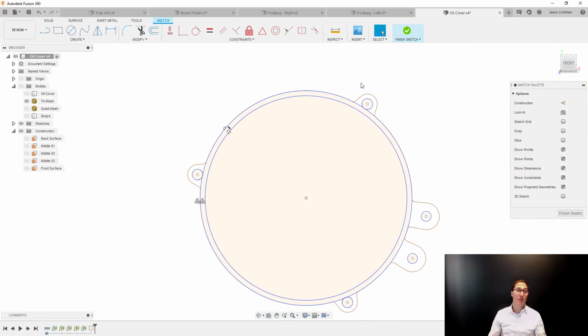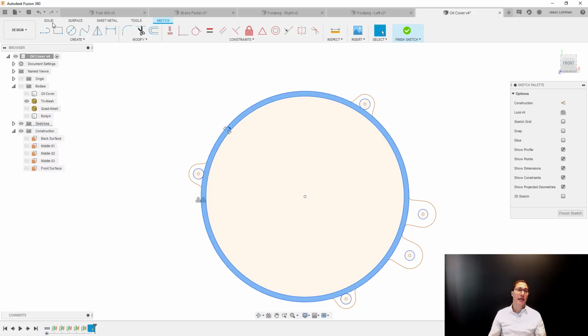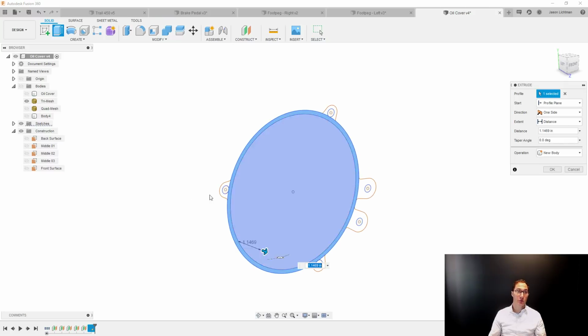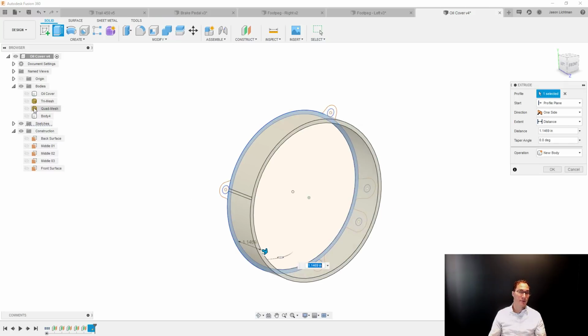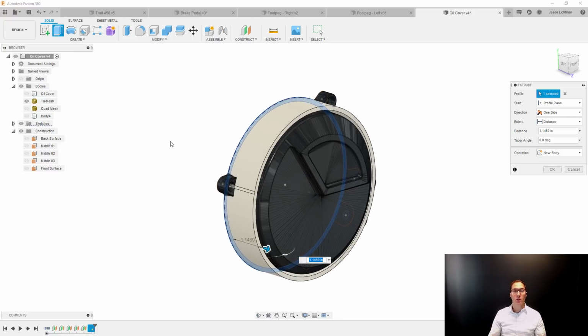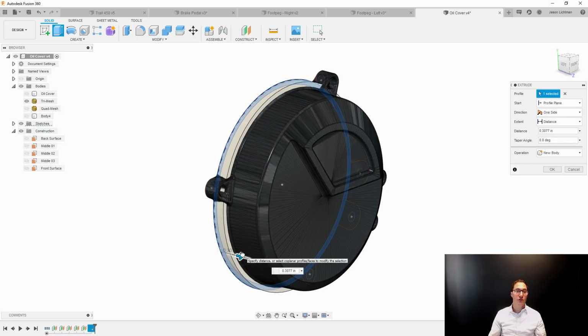And I can add my parametrics too. So I could have dimensions, excuse me, between the different sketches and different other entities. And when I'm ready, I could go and take this and I could use my solid modeling techniques like I showed you earlier, and I can extrude this. Let's go and show our bodies again. I could extrude this, start to add draft to it, or start to use other reference geometry of my mesh to figure out what I should do to end up with a solid model.